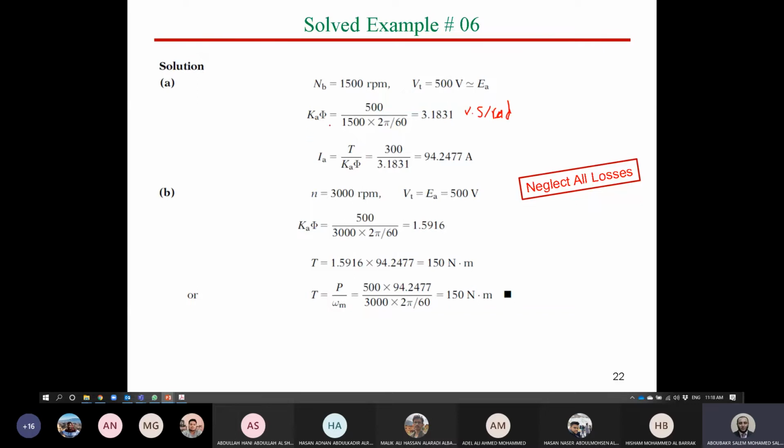Right. So this is now, شباب, the value of flux constant at the first region. Simply, we have the value of torque, so we can say now armature current equals torque over KFI and obtain the armature current. Right. Any questions, شباب? Is it clear? Good. Yes.